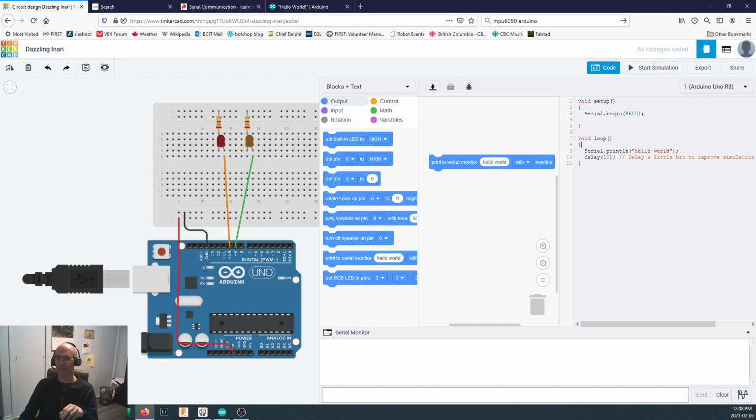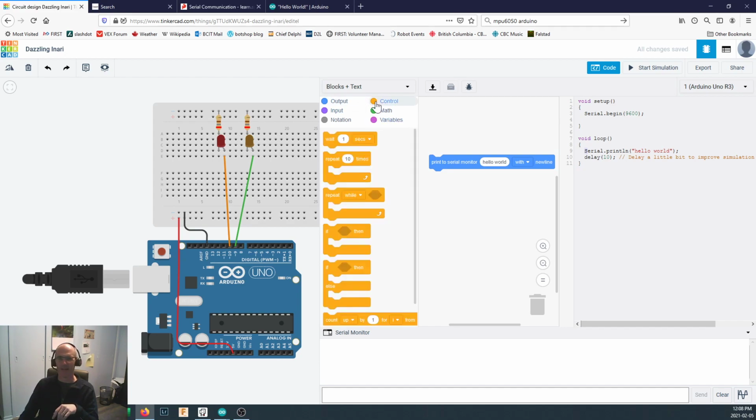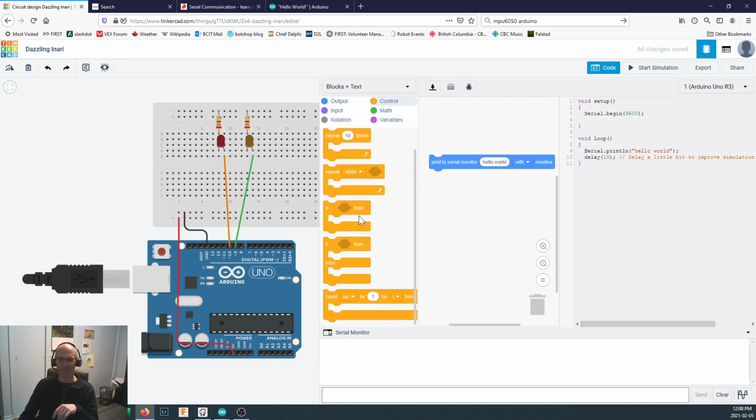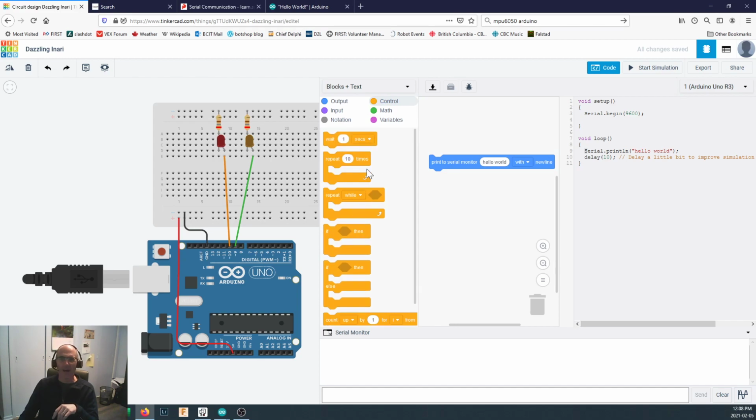Now, down here, you can see that we've got Serial.println. You'll notice that over here, I said I wanted to print this with a new line. We'll take a look at the impact that the new line and the ln at the end of our print statement does in just a moment. Let's change our delay up just a little bit. The delay of 10 seems, well, we're going to get a lot of data flowing in there if we have a delay of 10.